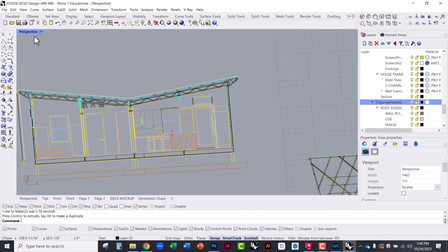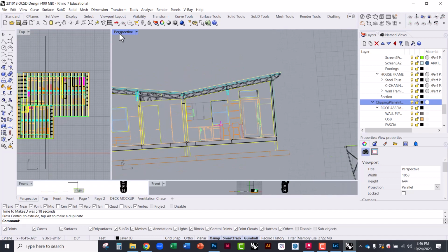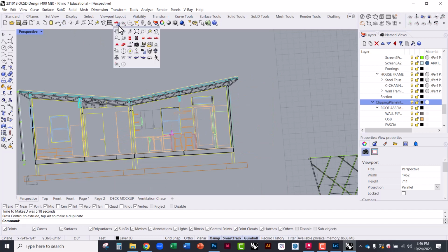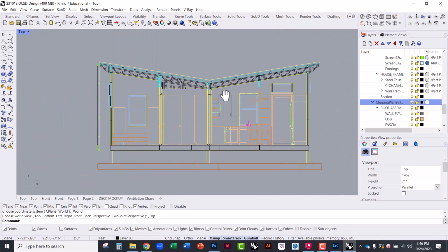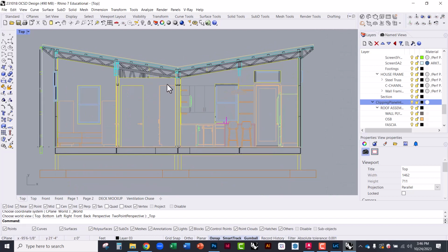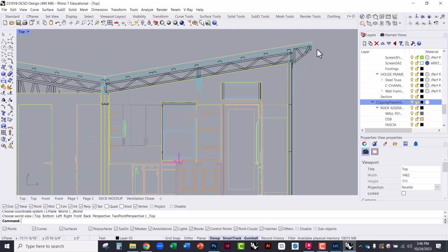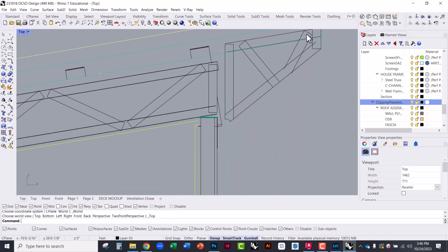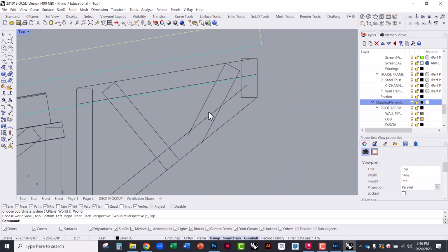And so I can go into top view, and now right click will just pan. And so I have this drawing, and it's a decent drawing. There's usually some cleanup involved whenever you do a Make 2D in Rhino. You'll want to clean up any extraneous lines, like when we zoom in on this, you don't want to see all of that.